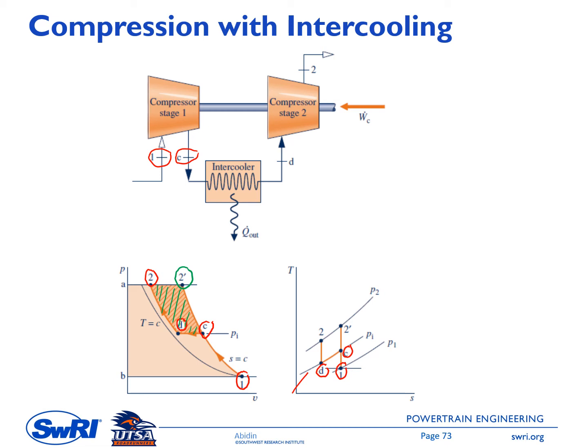So you have a certain targeted temperature at the exit of the combustor, state 3. But keep in mind, if we combine this intercooling option with the regeneration option, then the chance to get heat transfer from the mixture that exits the turbine increases. Why?